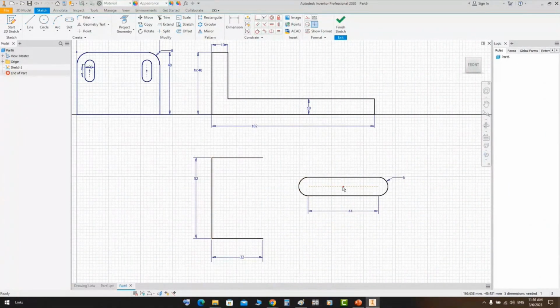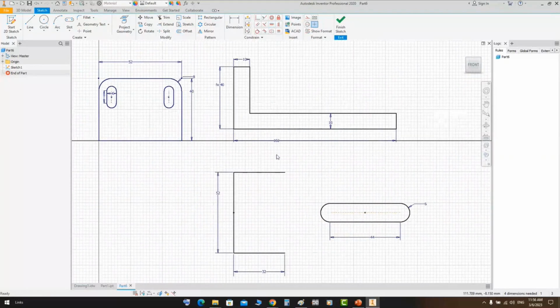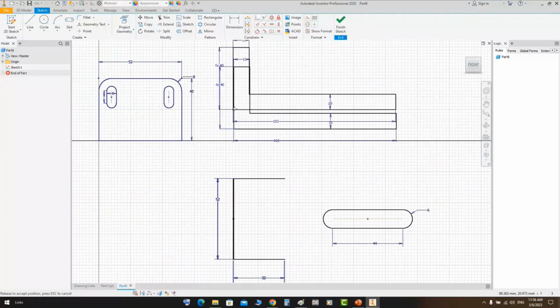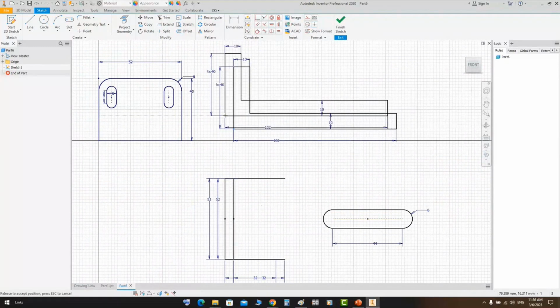So you will need to make a constraint that puts this point at the center here. As we did with the vertical, we will make it by using the horizontal. So let's select horizontal position and make this point at the same level as the horizontal point. Here you can see that you make them horizontal that way. Okay, and you can see that this sketch at the top moved up.